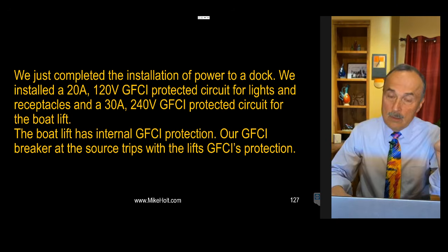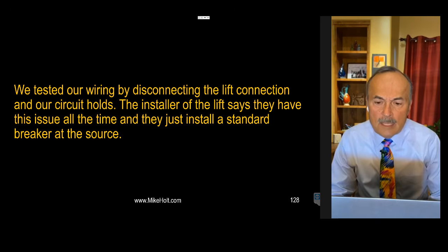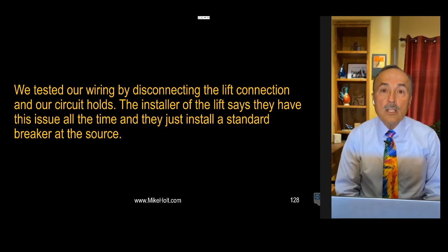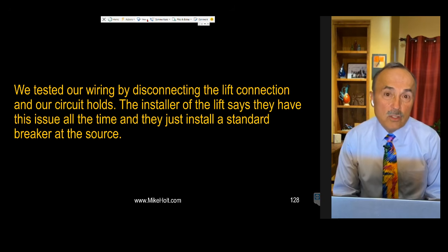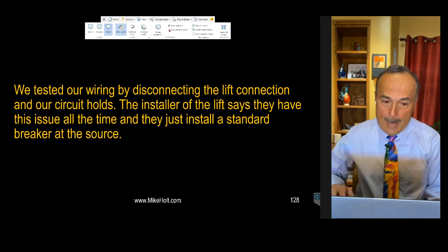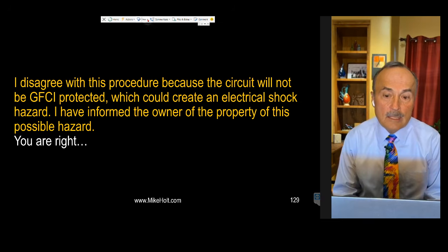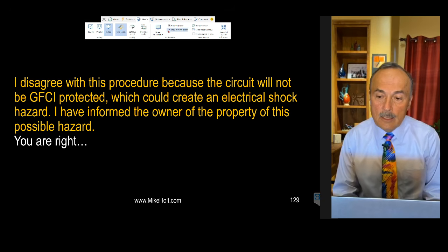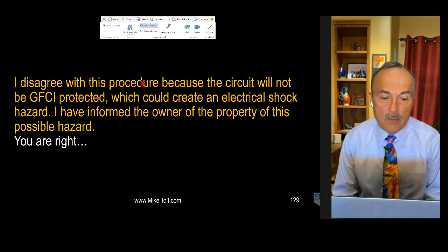And he says, hey, my GFCI is tripping. He goes on: we tested our wiring by disconnecting the lift connection on our circuit, and it holds. The installer of the lift says they have this issue all the time, and what they do is they just install a standard breaker at the source. I disagree with this procedure because the circuit will not be GFCI protected, which could create an electric shock hazard. I have informed the owners of the property of this possible hazard.